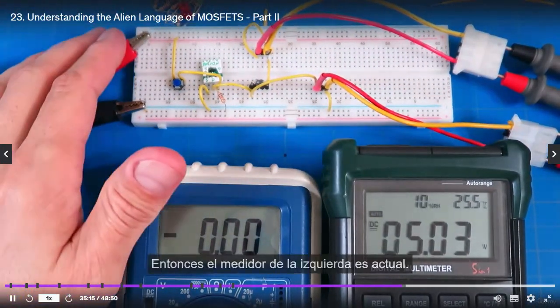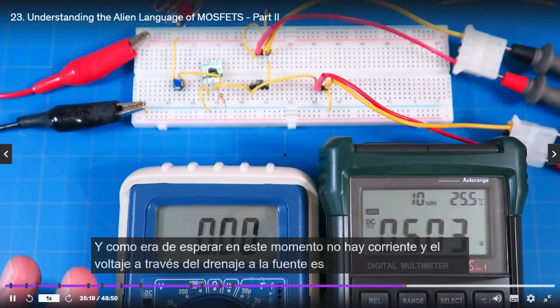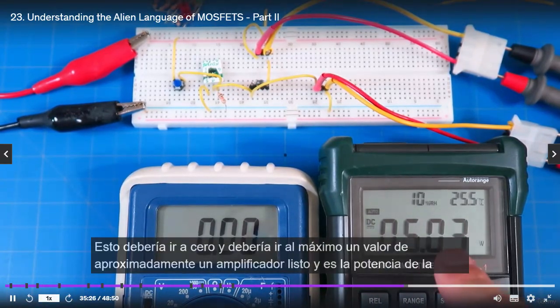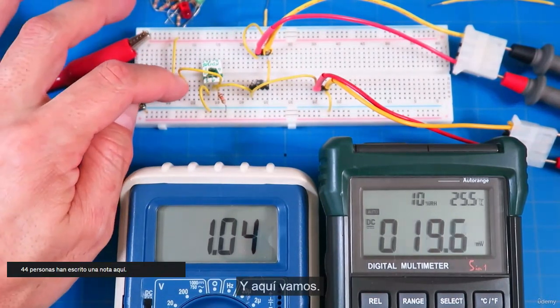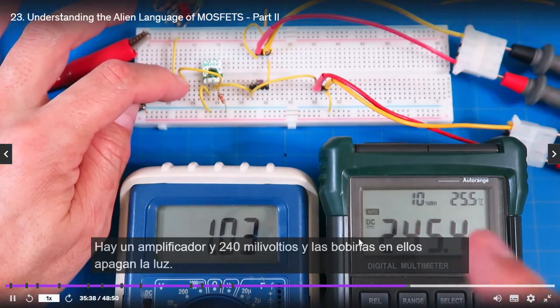Okay, so the meter on the left is current, the meter on the right is voltage, and as you would expect, right now there's no current, and the voltage across from drain to source is 5. When we turn this thing on, this should go to 0, and this should go to the maximum value of about an amp. Ready? And is the power on in the power supply? Yes, it is. And here we go. There's 1 amp and 240 millivolts.